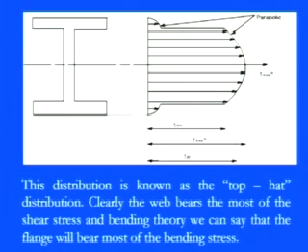So even in the flanges, though they carry only 5% of the shearing stresses, the distribution is always parabolic. Then we have tau minimum, as I told you, and it describes a parabola with the maximum value at the neutral axis, and then we can calculate tau average once we know tau maximum.